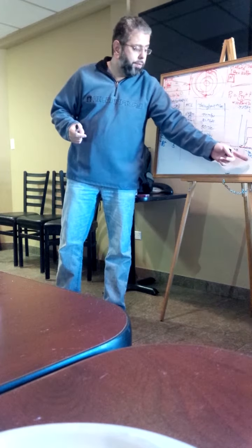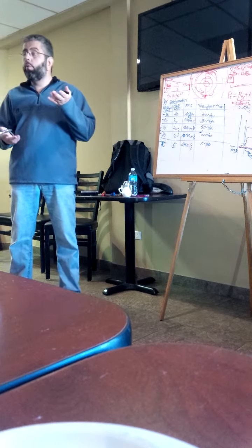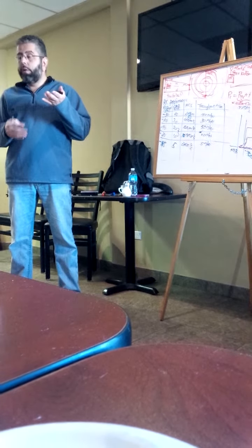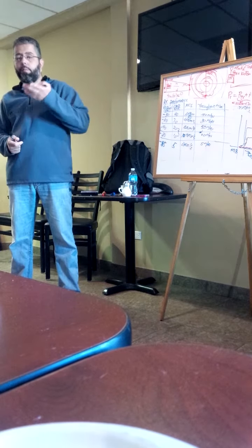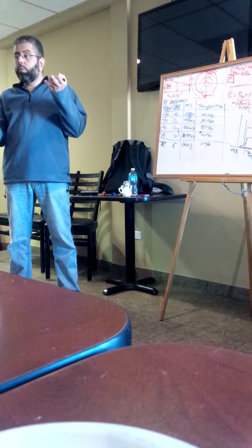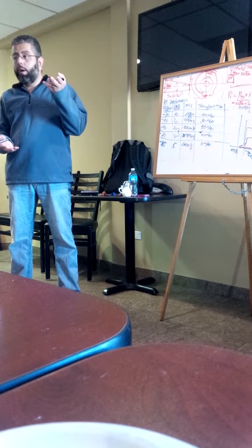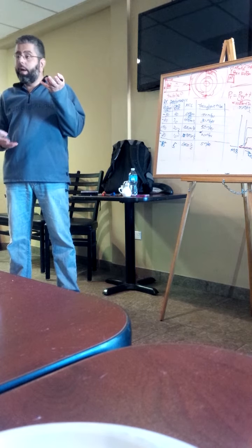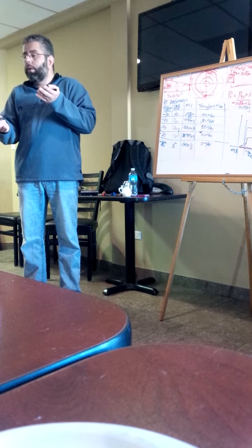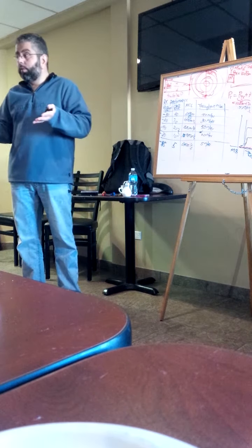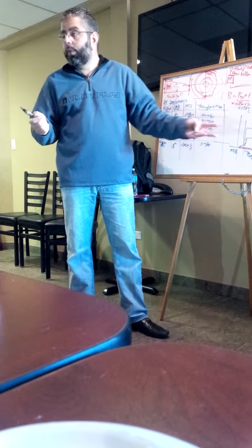It could be very close. Because when something is 25 dB below something else, remember we said 10 dB means something is 10 times lower in magnitude. 20 dB means that something is 100 times below it. So if I had something that was 1 watt, something that's 20 dB below it is 100 times smaller, so 1 watt compared to 0.01 watts. If you add 1 watt and 0.01 watts together, you get 1.01 watts. You convert that back to dBm, it's still the same dBm number, right? Because something 25 dB down below is not going to impact it much when you add them together.